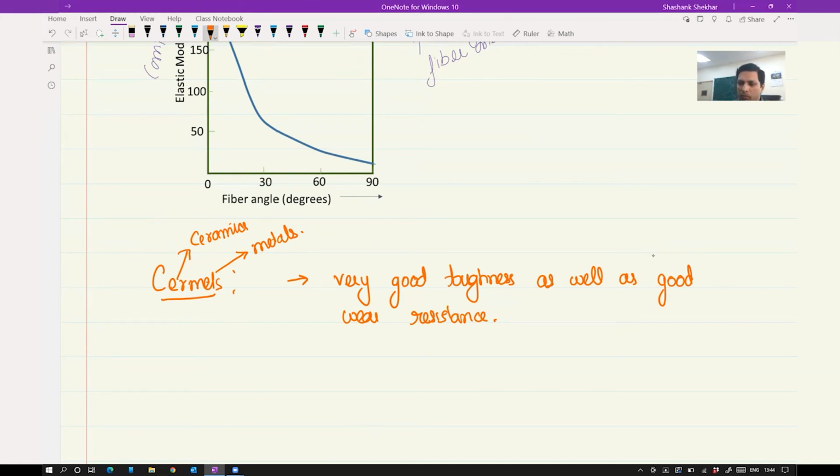Strengthening also depends on particle size. Small particles cause strengthening by dispersion hardening and improving the load carrying capacity of the matrix. On the other hand, larger particles share the load with the matrix, and proper bonding is very important in the case of larger particles, and they are able to transfer the load from the matrix to the reinforcing phase.